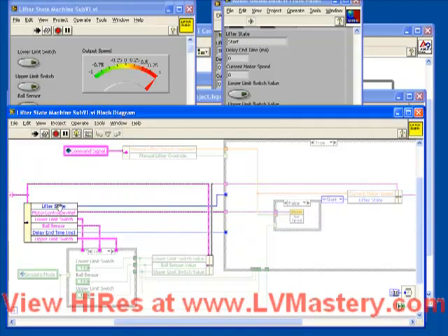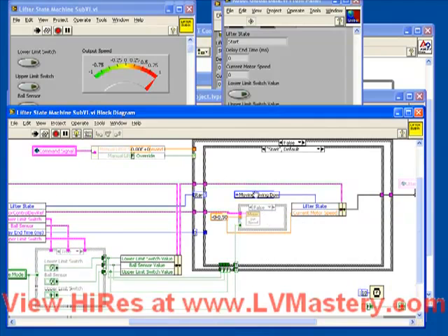We see that our initial state is start, as we expected. Our command signal is 0 and false, which is good. Our simulate mode is true. Our three booleans are false. So we immediately go into the start case. Our output speed has been set to -0.5, and our new state is moving down. Then as we watch, we see we go into the moving down case.